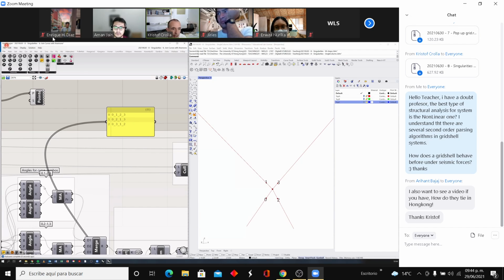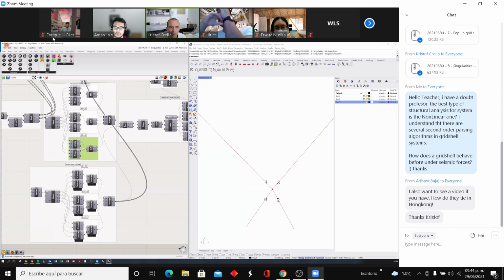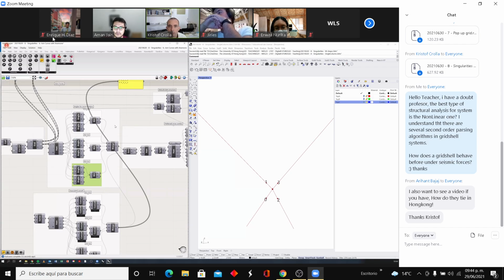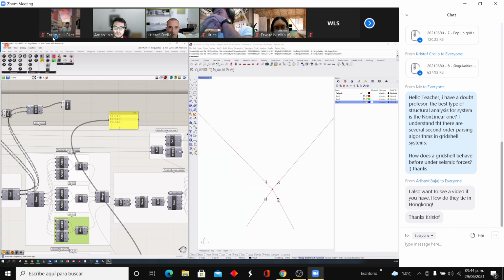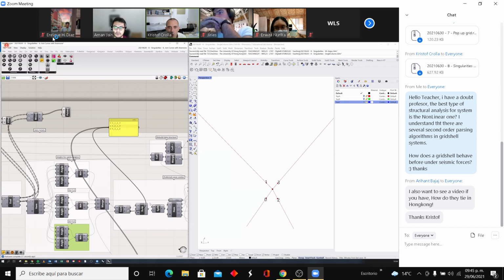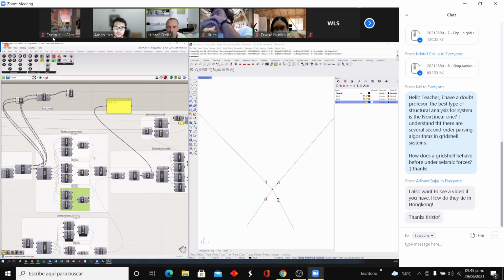I just generated that using a simple series button. So this is just text that I have. It's basically the titles of my 3 blocks here. So I'm sorting that simultaneously with my angles. Right now I know that an orientation of 0, 3, 1, and 2 is the best way to connect my curves. So connect curve 0 with curve 3 and curve 1 with curve 2. I've just sorted that in a similar way as I've sorted my numbers here.